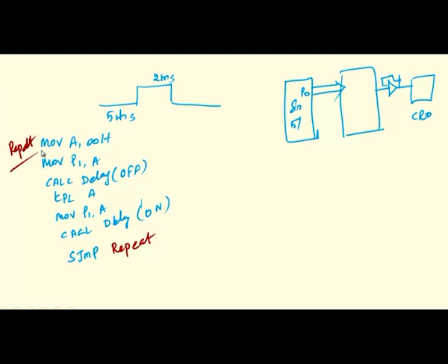Okay. So, from here to here it is jumping, we are getting the values of 00 and FF, right. So, this is an on delay and an off delay, only two different delays we have varied. Okay. So, now we will discuss how to write the delay program or how to calculate the delay value.